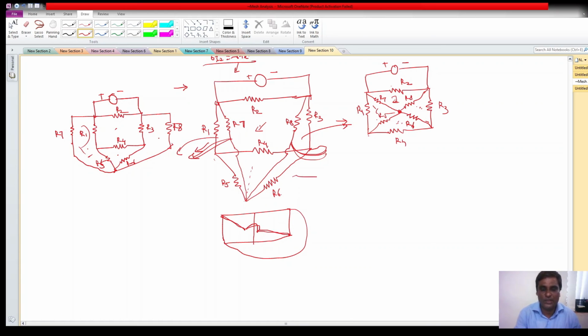So that's why generally the circuit should be planar to apply mesh analysis, because obtaining the meshes is difficult. And there are so many ways to convert non-planar into planar, but the meshes will not be the same. So we can conclude that mesh analysis is a somewhat weaker method than nodal analysis. So with this we stop here.